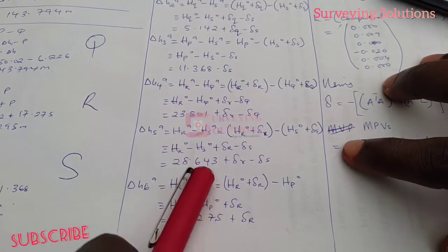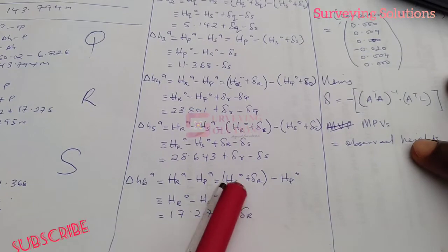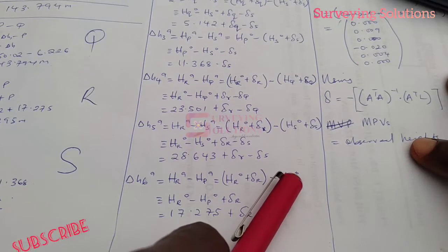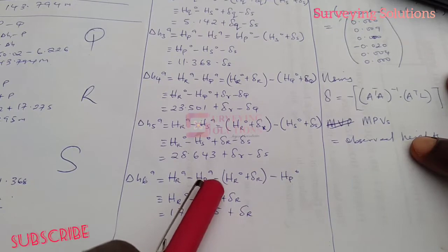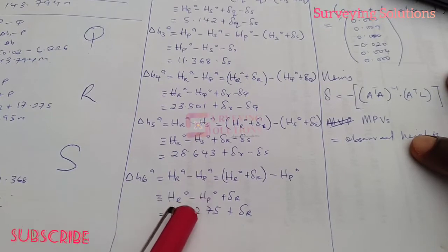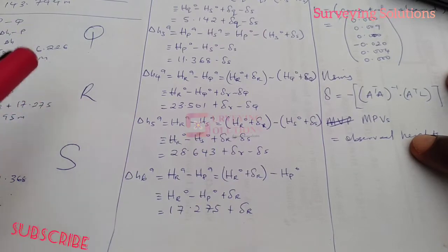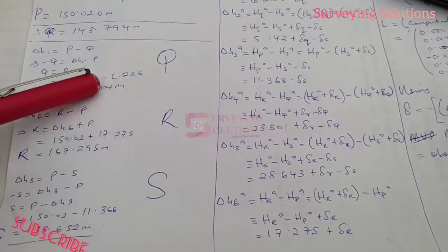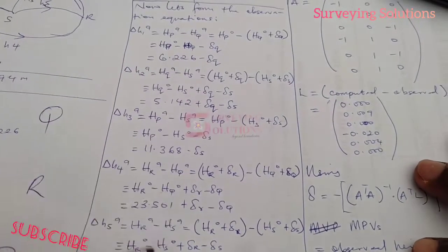Since we know that p does not have any error because it's actually our benchmark, it's only r that has error in this case. So we have the height of r observed plus the error in r, minus the height of p observed. Are we together? So in this case, we just have this minus here. So this minus comes to meet its partner here, which is the height of r. So we have the height of r observed minus the height of p. So all these heights we are talking about, whether it is q, r, or s, we are using the provisional or the observed heights we have gotten here. Are we together? So that's how you form the observation equations for all of them.